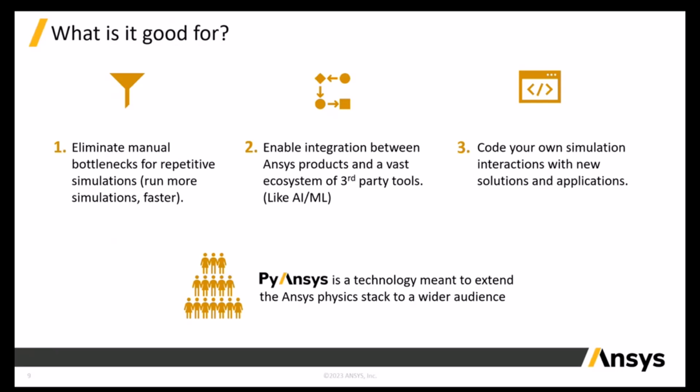So what is it good for in a very summarized way? One, eliminate manual bottlenecks for repetitive simulations. So run more simulations faster. You have to code all the script to do it, but it's absolutely possible to use a PyAnsys script to run 10 or even 100x the simulations through, say, ADT, using a script rather than using the user interface.